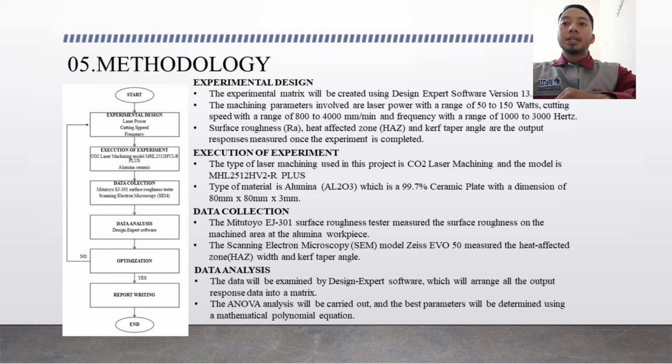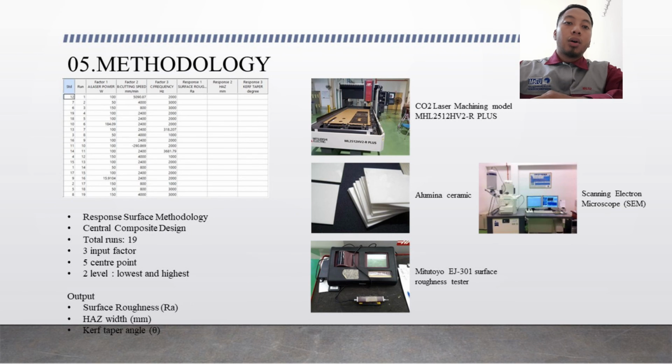And for the data analysis, the data will be examined by Design Expert software, which will arrange all the output response data into a matrix. ANOVA analysis will be carried out, and the best parameter will be determined using a mathematical polynomial equation. The type of design of experiment used is response surface methodology or RSM, and the tool is central composite design or CCD.